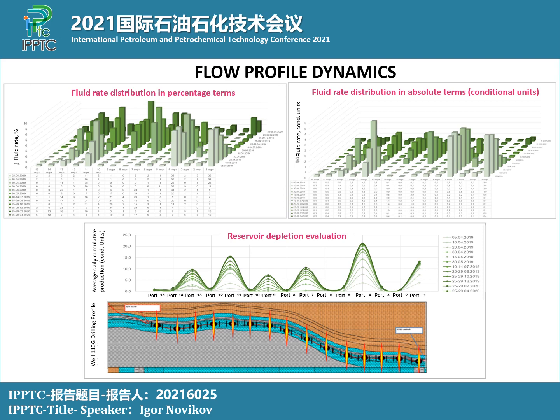We can analyze the green curves here, and by looking at them, we can say that only 30% of the 15 ports give us any inflow. So there are 6 ports which actually drive this well and give some fluid from the formation, and the other 9 ports are mostly not working or give us very little volume of fluid.